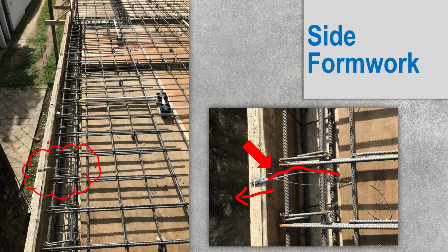And also you can see here they have fixed it at regular spacing, but if something goes wrong in one place, as they have fixed this with a nail, this whole thing will collapse. Therefore it is recommended to use side support rather than these kinds of temporary things.